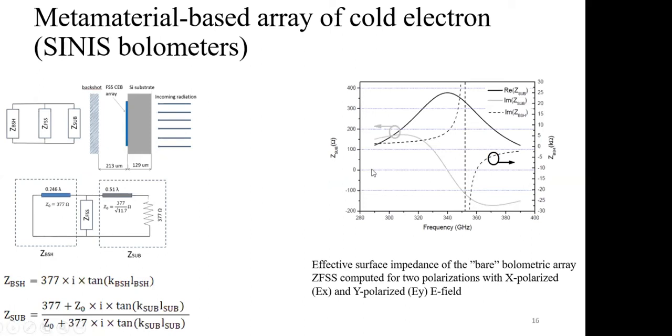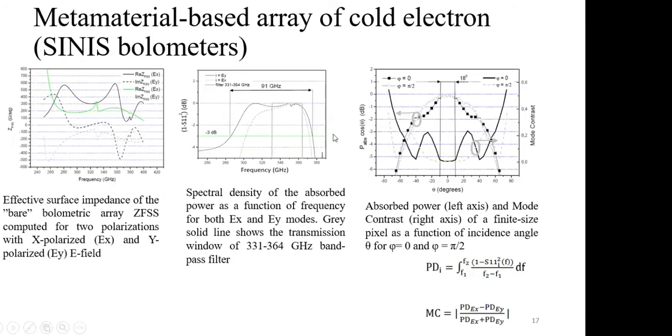And the final result can be observed here. For the frequency selective surface, we can see it's not the same, but fortunately the absorption also has a large bandwidth, more than the previous design, and they are the same. So we have a design which is not symmetric, but the result at the target frequency is symmetric, and we increased the bandwidth.